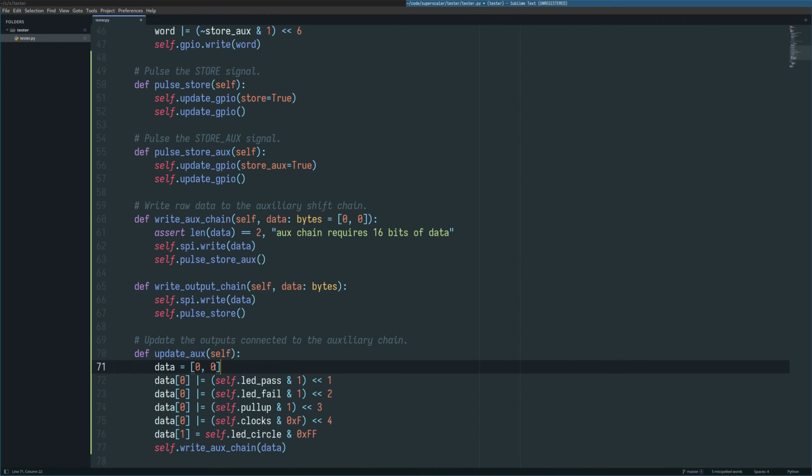And so what this would mean here, if we have a long list of data, is that the leftmost element would end up in the rightmost place on the actual physical board. And the last element in the list, which is the rightmost in how you would read it and look at it, is going to end up in the leftmost position of the board, basically the one that's closest to the Adafruit, because it's the last thing that gets pushed out. And so to make this more convenient to work with, I think we want to reverse the data here before we shift it out over SPI.